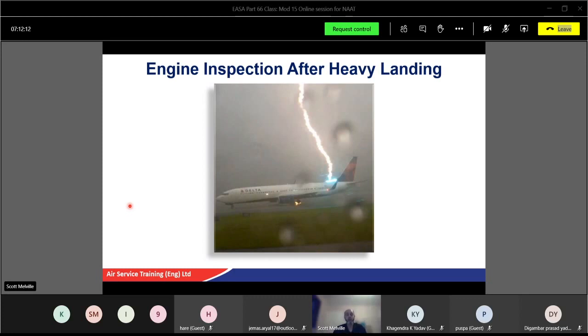So we're trying to keep the engine as long as possible. So Rolls-Royce, who manufacture the engines, said we need to derate them just to give them a bit more length of time in service. So we reduced that flat rating a little bit and we tweaked the engines back. They lost a little bit of thrust, negligible, hardly anything. It just gave a few more hours for that engine.